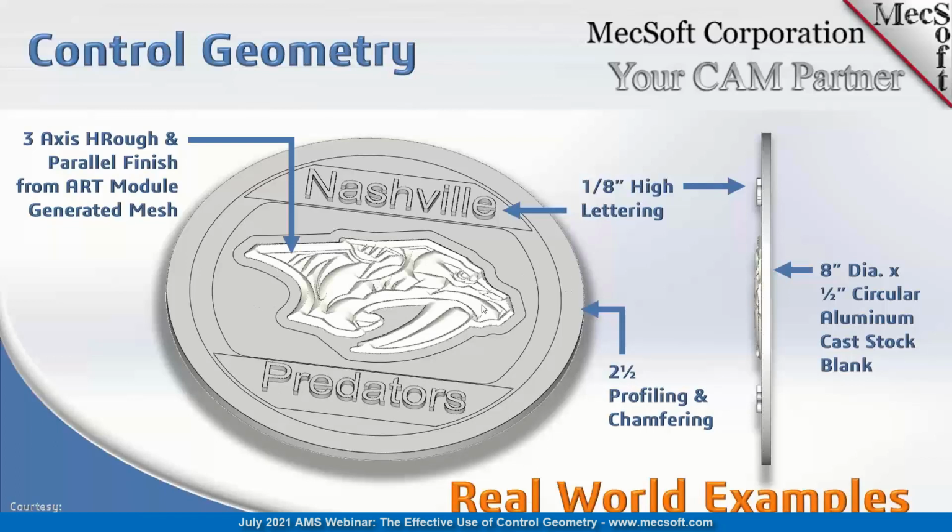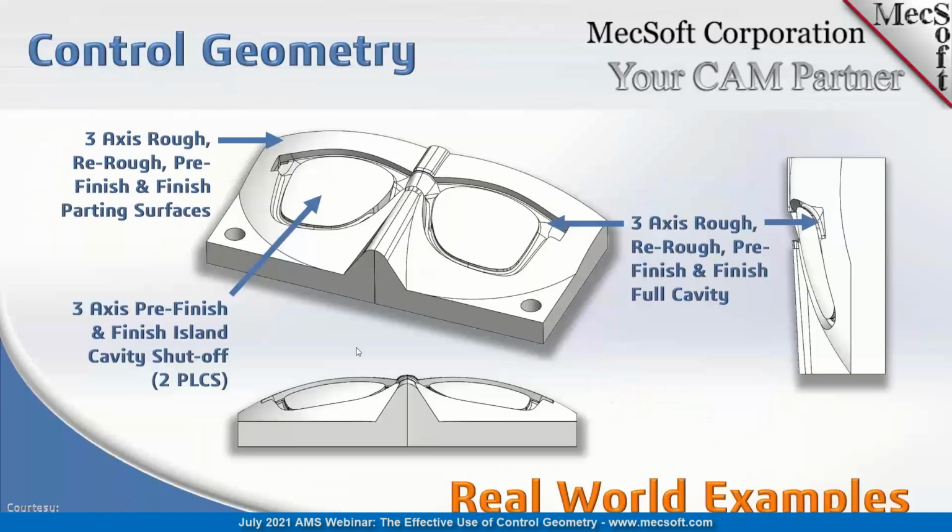And then this is a Visual CAD example. In Visual CAD, we then added obviously the lettering, and the cylinder as well, located at the base of the mesh. So we got 3-axis roughing, finishing, we got lettering, 1/8-inch high lettering above the base surface here. And then we have some profiling and chamfering going on at different places. And we're going to be looking at this part as well. So the next part.